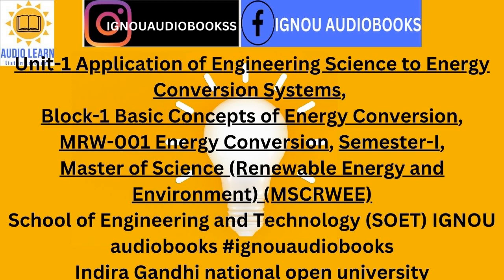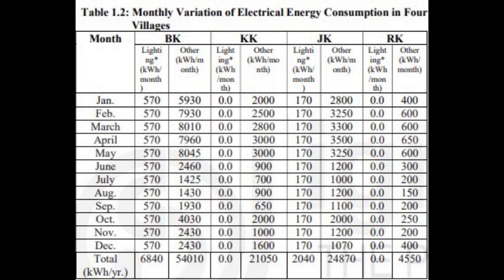For example, if only the output of electrical energy from a power station is regarded as useful, you can see from the figures above that the conversion efficiency is quite low, being 30%. However, if some of the heat output can also be utilized, the efficiency could be as high as 80%. As you know from the mainstream, this is the main consideration that led to thinking about combined heat and power stations.